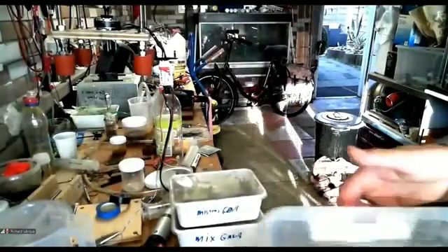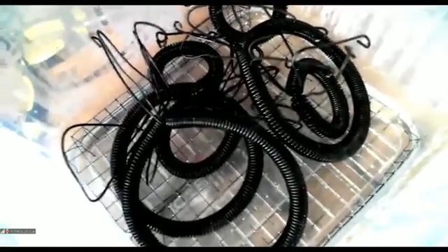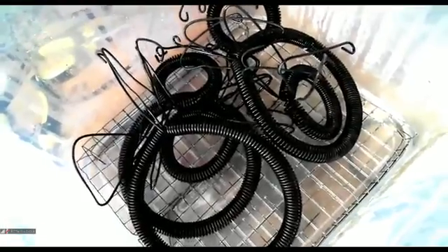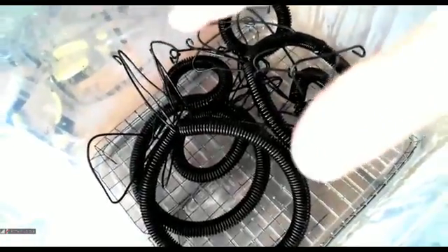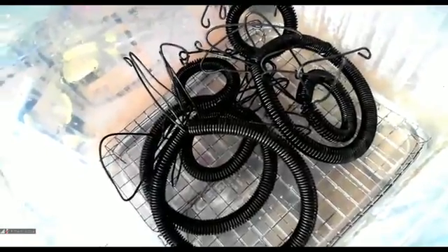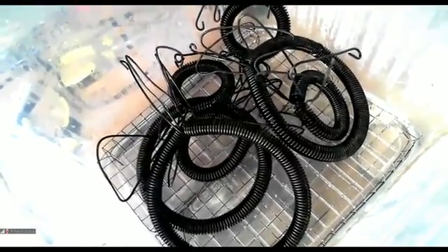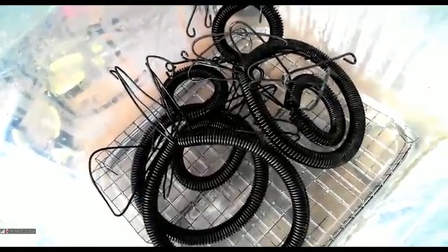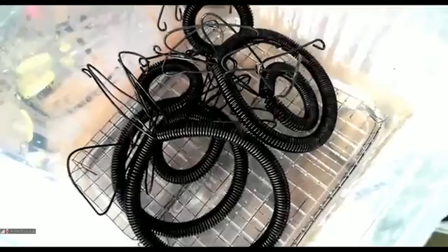What you have to keep in mind is that these coils in this situation are still wet. So they're still moist, and that makes a big difference in appearance. They really look black, with no gray stuff and no crystals. But when you have a caustic situation like this and you leave it this way and it dries up, it will start crystallizing. So you get the white crystals on there. Those are the caustic crystals. For now they're a bit wet, so that makes them appear really black.